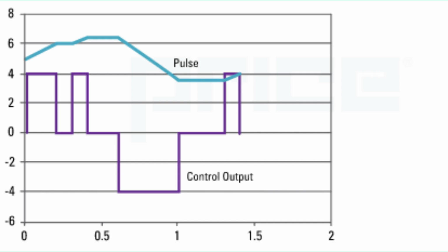F. Time proportioning or pulse width modulation. Turns on and off rapidly within a time cycle. For example, on 7 seconds, off 3 seconds in a 10-second cycle. Used for electric heaters or staged systems that can't modulate smoothly.